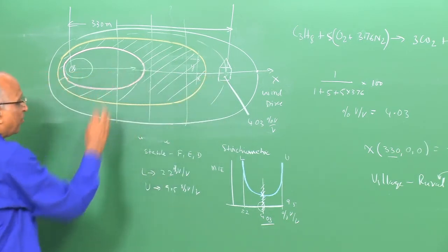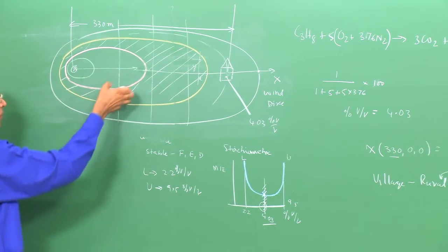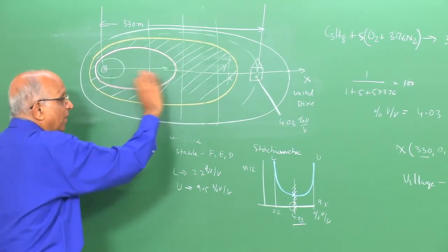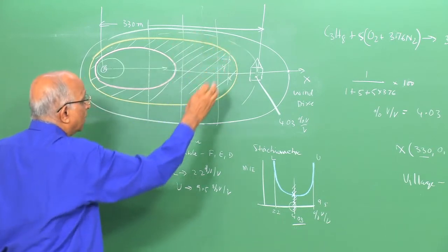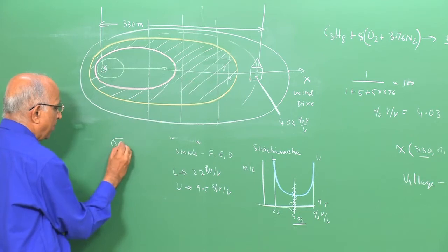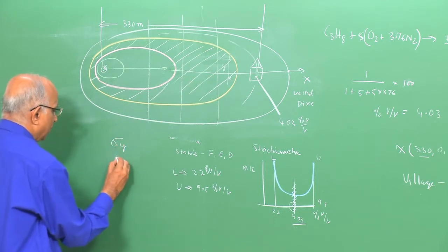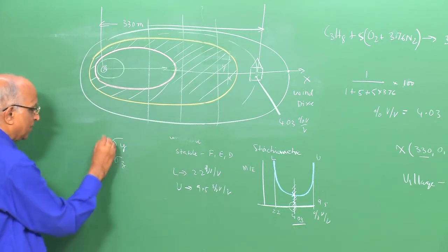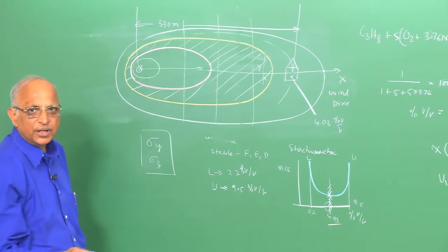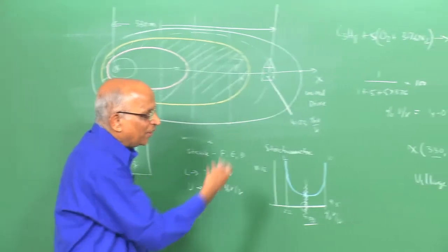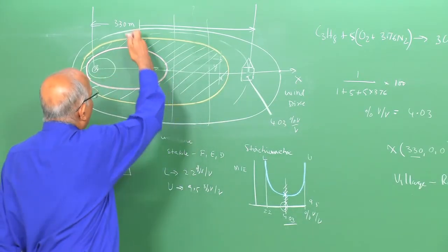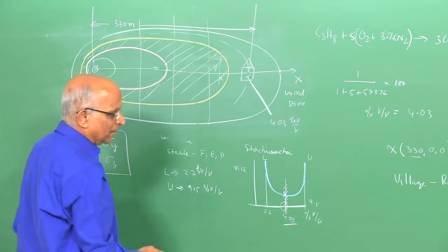Therefore, in such problems we are able to take care of the different conditions of the atmosphere, like a cold winter night, the wind condition, the cloud cover, and solve it using the determined parameters of the dispersion coefficient sigma y and sigma z, which are calculated for the particular atmospheric conditions. Well, this is how we do problems on atmospheric dispersion, and this is how the problem of the case of Port Hudson leak is done.